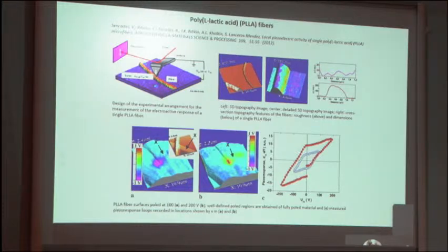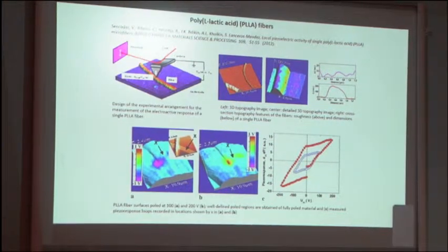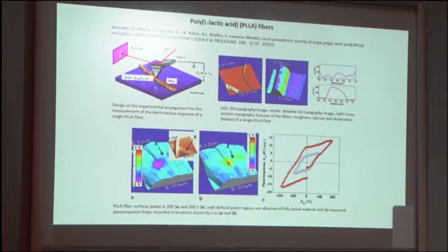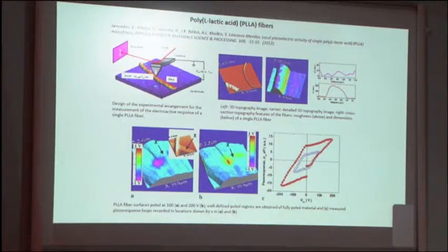For organic materials and biological materials, very often piezoelectric property is not present at the beginning, because microdomains or layer structures are organized with opposite orientations of polarization, and in this case we detect at the beginning that piezo response is 0.